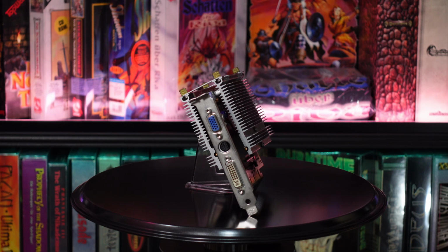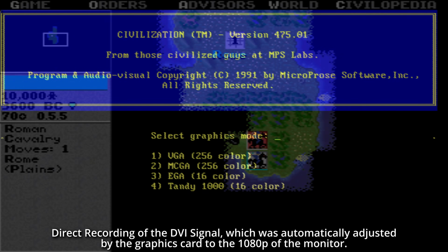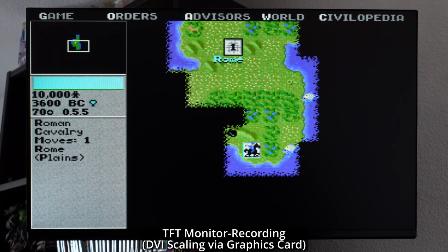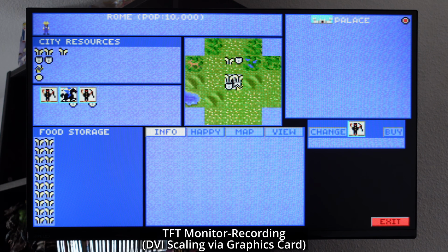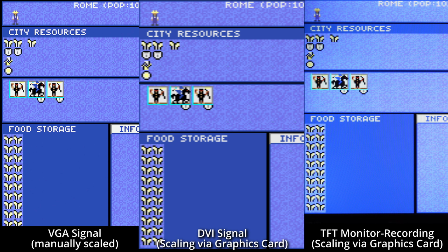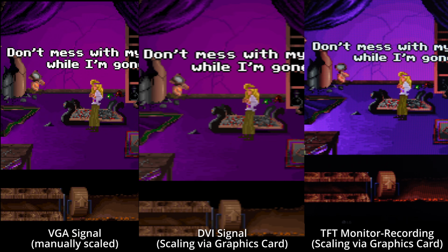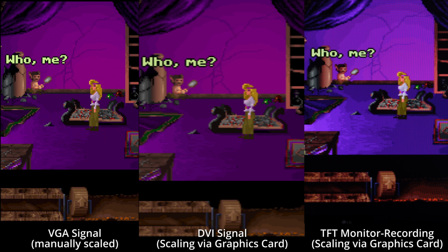Even if you got a graphics card for that, you might still encounter problems if you go into DOS mode or start games with low resolutions or high refresh rates. It is possible that your graphics card already converts this signal internally to a more compatible DVI standard, and while the result probably looks rather bad, you would at least be able to see anything. But this is very dependent on the individual graphics card. It is also possible that you simply get a black screen and maybe an out of range warning.